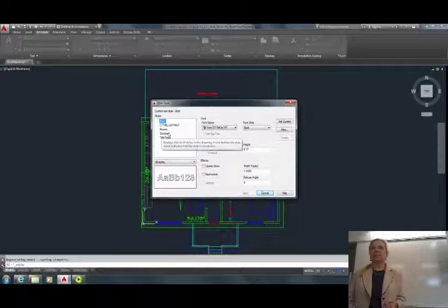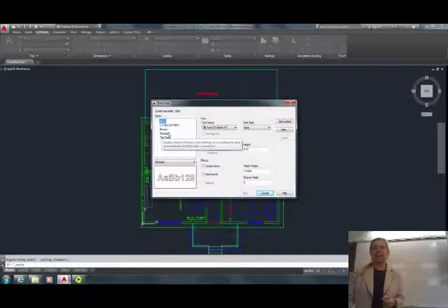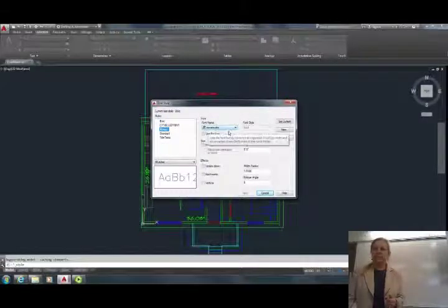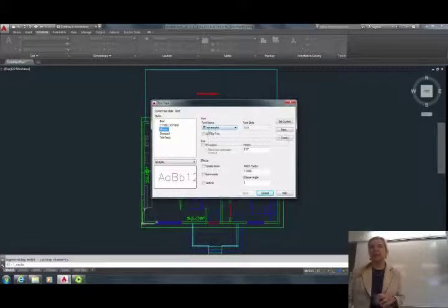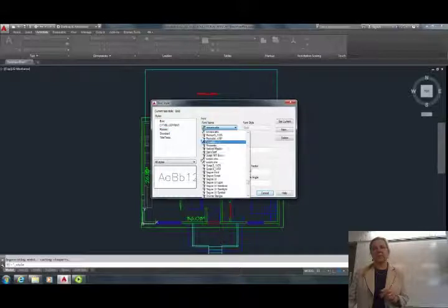You should have it, but if you don't have it yet, I would suggest you use the Roman font, Roman SAH, because all of the fonts that have, believe it or not, this miniature compass, I think, all of the fonts on the list that have the drafting compass beside them are one line, and they are best for AutoCAD.